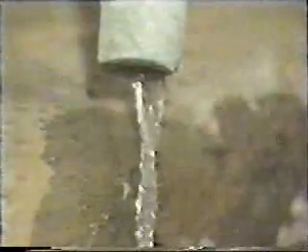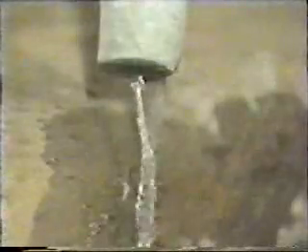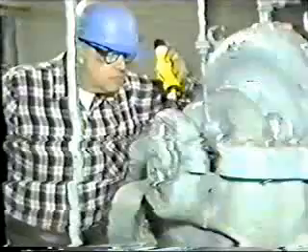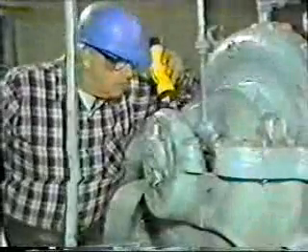The runoff on the outboard packing seems quite heavy, just as the operator has indicated. Although the fluid in this pump is water, other pump fluids may require special safety precautions. Be sure to follow your facility safety precautions when checking runoff. Check for the source of the excess leakage.